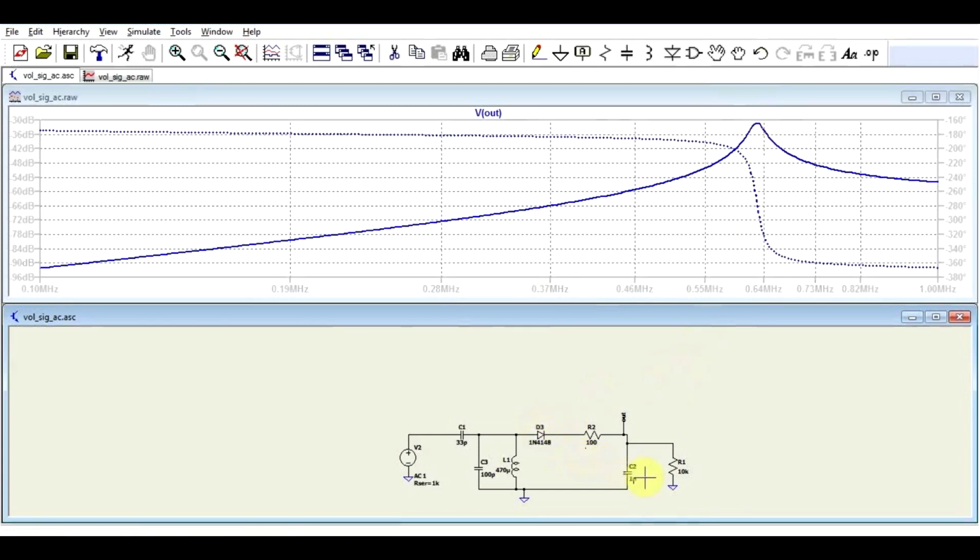But this time we're talking about a DC signal, and this is what is going to be used to drive our voltage controlled amplifier. As long as the frequency of the oscillator is very close to this resonance point, any small variation in its frequency will have a large variation on the output voltage. And this you can use to vary the volume of the final sound. So let's see how this entire thing would look like put together.